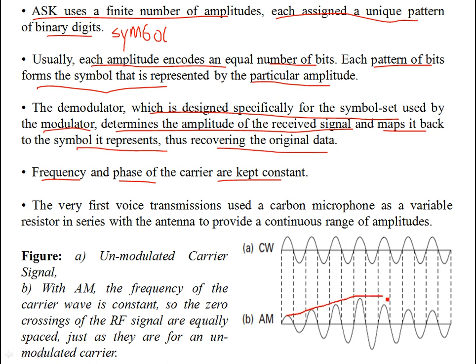When the amplitude is high, the modulated envelope is high. The envelope actually catches the shape of the modulating signal. So as the amplitude is high, the output AM modulated waveform amplitude is high. That's how it looks in the time domain. When the amplitude of the modulating or message signal is low, you have a low variation of amplitude, and when it is high, the modulated waveform has more strength. That's how you are producing the variations in the amplitude, and this variation is continuous.